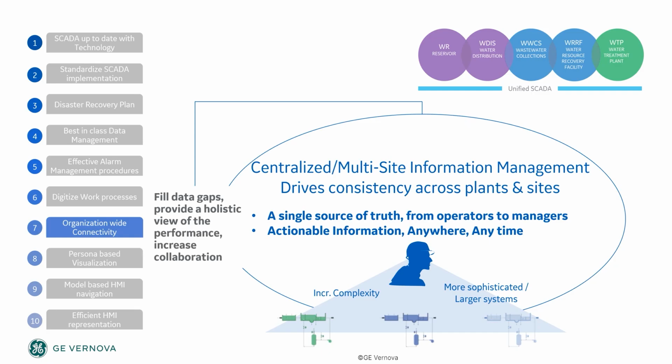Now, this, I understand, is probably the most complex part of getting people to adopt, right? It's not easy to get a water treatment operation to follow the same consistent look and feel, or even the same SCADA, as the water distribution side. Each one makes the decision separately. And what we have seen be most successful is if we start that process by having a common visualization layer. And when you start with a common visualization layer, you have to start with stakeholders that need data from your systems but are not directly connected with operations.